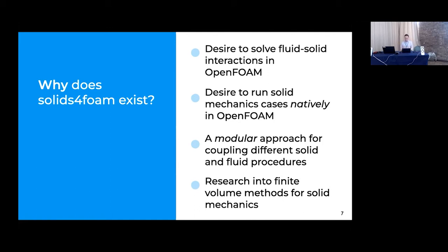And also the idea of a modular approach. So for some of the earlier FSI work, I released a solver in the OpenFOAM solid mechanics toolbox called icoFsiNonLinElasticULFoam. It's basically picking icoFoam with a particular type of solid formulation and just putting them in one OpenFOAM solver so you can run it. Then I wanted to change it from icoFoam to pimpleFoam. So then I'd have to make pimpleFsiIco and so on. So that's a real pain for code duplication.